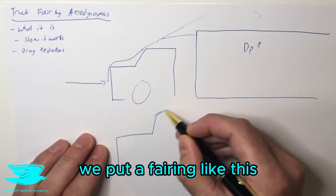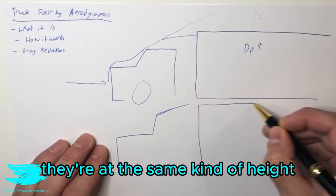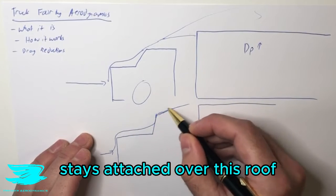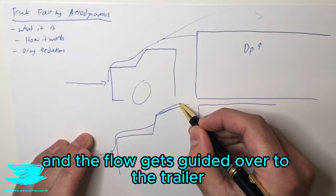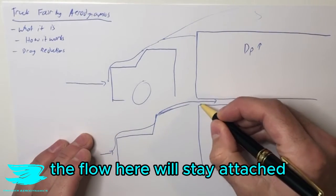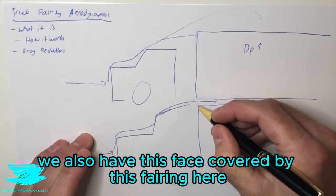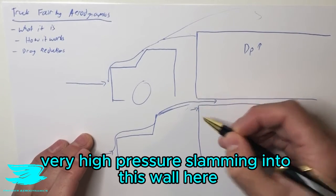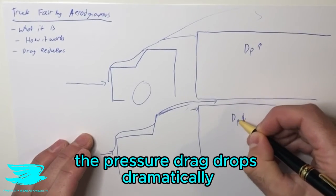We put a fairing like this, so that when it intersects the trailer, they're at the same kind of height. So the flow comes along, goes up over, stays attached over this roof, because it's now a little bit of a slant, and the flow gets guided over to the trailer, and ideally, the flow here will stay attached. So we have not only attached flow over the trailer, we also have this face covered by this fairing here. So we're not actually getting very high pressure slamming into this wall here. As a result, the pressure drag drops dramatically.